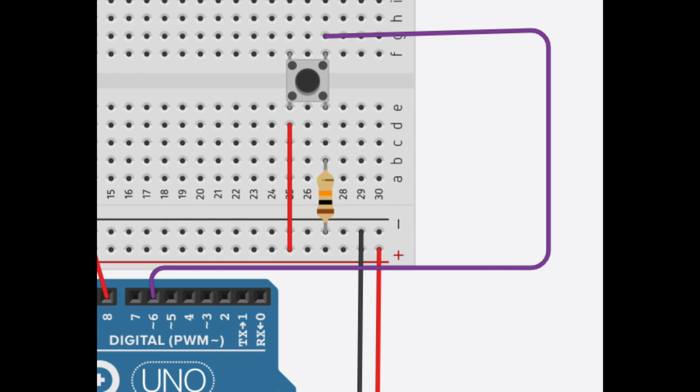It is connected to ground, and opposite of the pull down resistor you can see we connected to Arduino's digital pin 6. I told you already that pin 2A and 2B are internally connected, so 2B is directly pulled down to ground, and that's the reason by default we are getting the value 0. But the moment I press this momentary button, 1A and 1B get connected, so this Arduino pin 6 gets connected to 5 volt. That's the reason we are getting logical high.